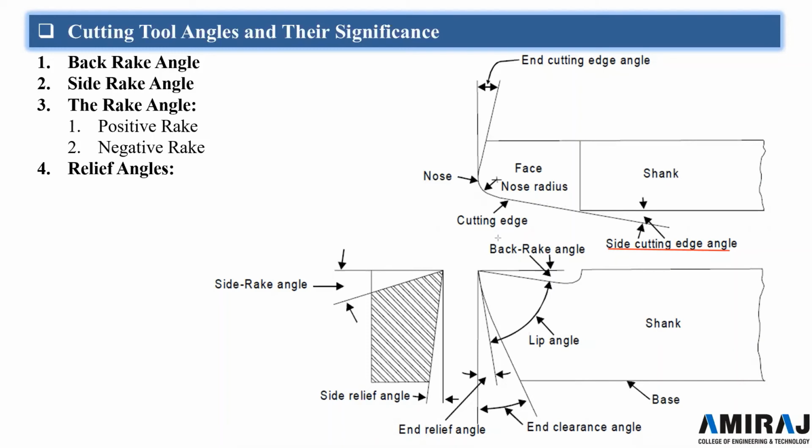Now, the side cutting edge angle of the tool has practically no effect on the value of cutting force or power consumed for a given depth of cut. Larger side cutting edge angles are likely to cause the tool to chatter.